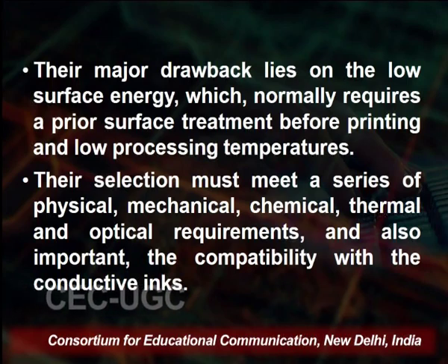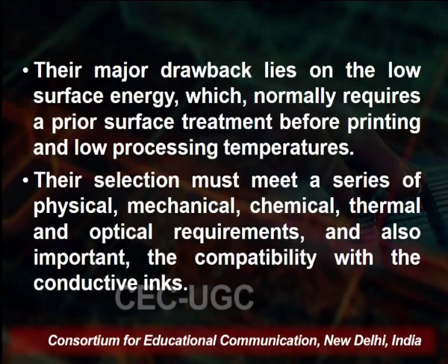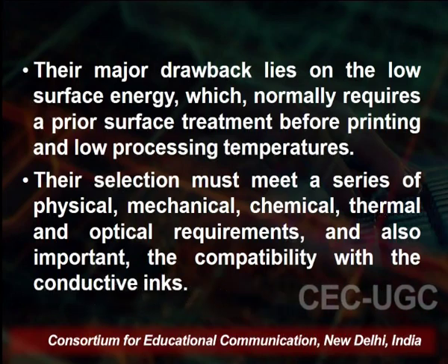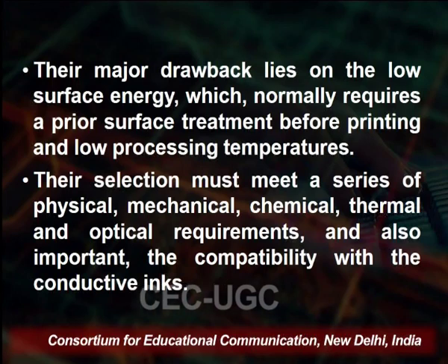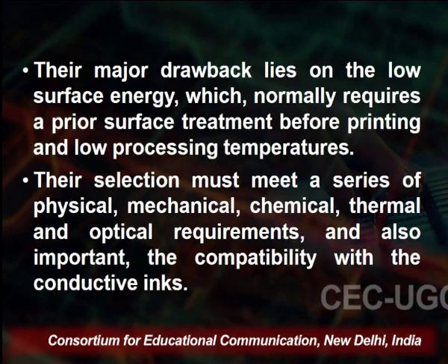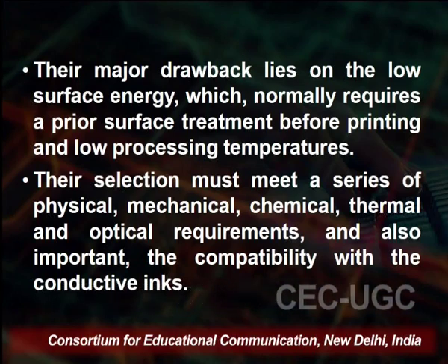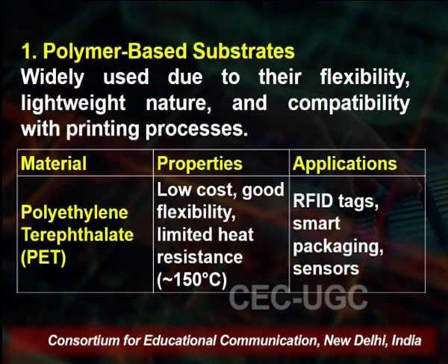So, the selection of the substrate must keep in mind its physical, mechanical, chemical, thermal and optical properties, and also it is important that it must be compatible with the printing ink. It may be conductive, insulating, or semiconductor ink. So, the substrate must be chosen according to the ink we are using. If we talk about polymer based substrates, they are widely used for their flexibility, lightweight nature and compatibility with the printing processes.